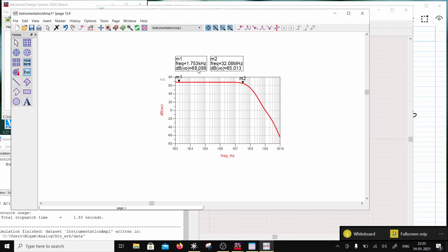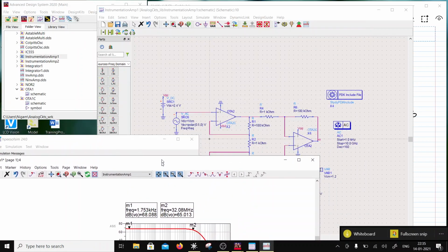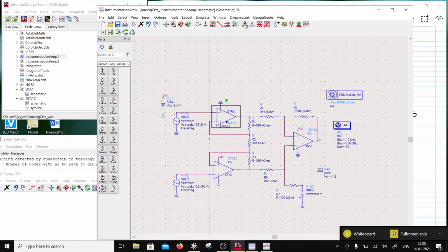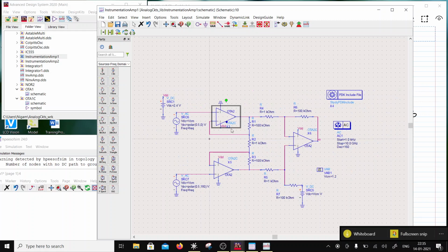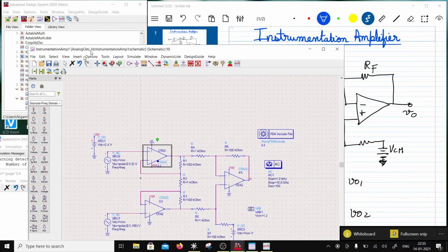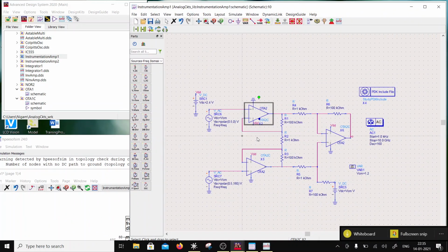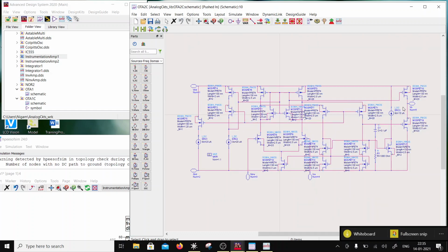Now I'm trying to wonder why I'm losing the gain. If I go inside, I have an output stage which can deliver current, right? So if this can deliver current, then this should be just a function of these resistances, right? So it should give an 80 dB gain, while it is not giving an 80 dB gain unless the gain of each one is messed up. And what is going to mess up is the current drawn from this node. So if it is a follower, it should not have a problem, right?